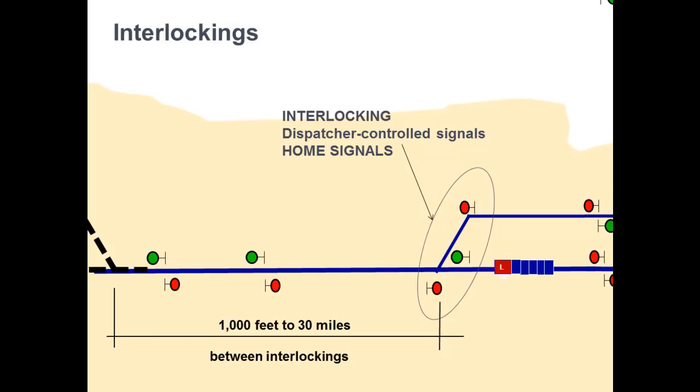If something is detected, for example, a train, or if there is an ice mass or rock in the switch points, the interlocking signal won't clear. If it is cleared, the train can operate in accordance with the signal, and the train proceeds. Note that if the train was going to make a diverging move, the switch would have to be thrown by the dispatcher prior to the signal being cleared.